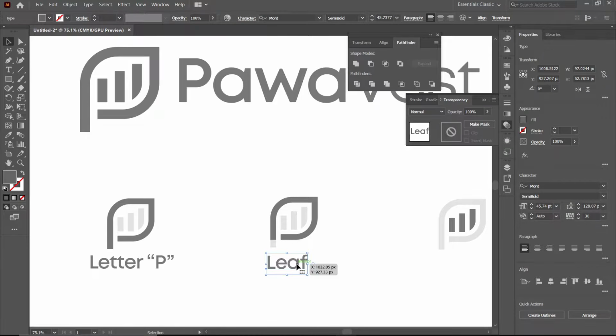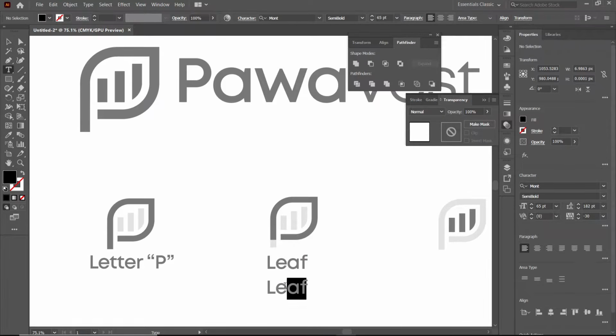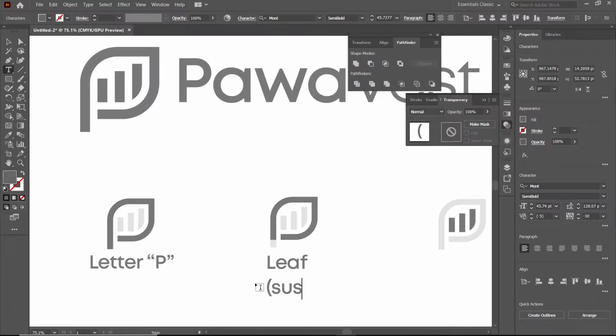For this purpose, again hold down your left mouse button, then hold down the alternate key and drag it like this. Select the type tool and simply write sustainability. Now again select the selection tool and reduce its size like this, because this one is the secondary part.